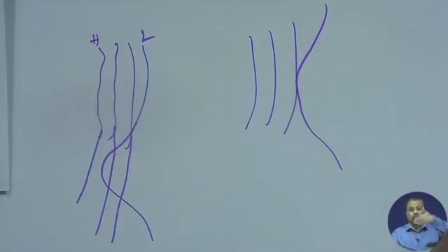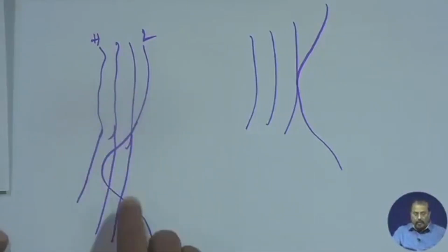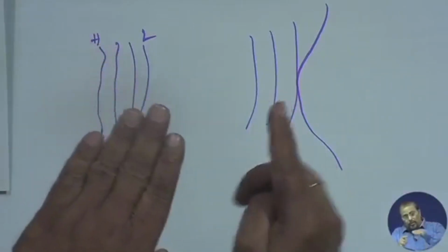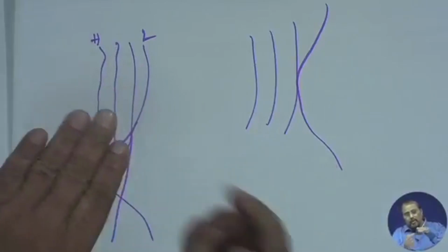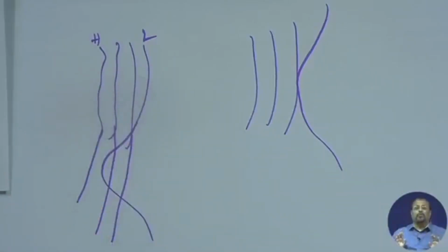So there is a vertical face. Keep that in mind in the contour analysis. And if it is entering into this, then there must be a cave, this is overhanging, and the lower level contour has entered into it as a cave. So this is a cave situation. If you understand this, then your contour interpretation will be very, very effective.